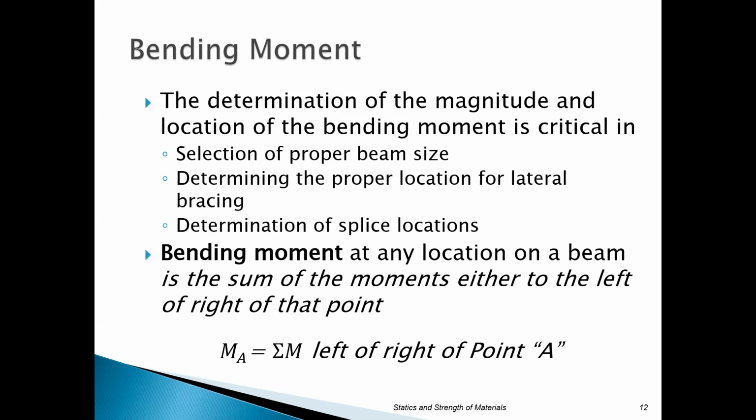Just think about that. What would increase the moment of inertia that might size that beam so that they don't have as much deflection? How do you increase moment of inertia on an I-beam? Make it thicker. Thicker which way? Basically, Jacob, if you just increase the depth, the distance from flange to flange, if you look at those charts, that will directly increase your moment of inertia. So make it taller, basically.